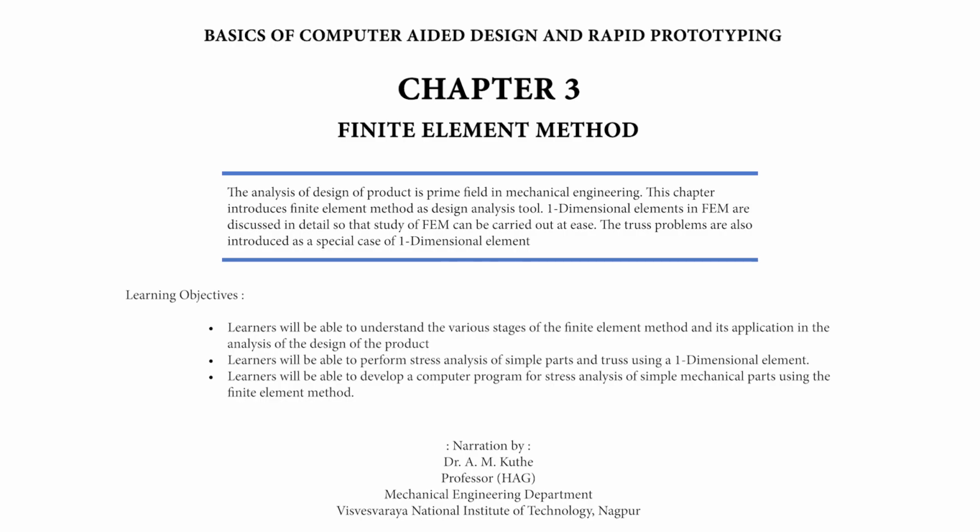For example, in the design of the shaft, the diameter of the shaft is decided considering the maximum stress induced in the shaft. It is possible to reduce the diameter of the shaft in other regions of the shaft where stress is less than maximum stress. By reducing the diameter at a separate section, it is possible to modify the design of the shaft. Refer figure 3.1.